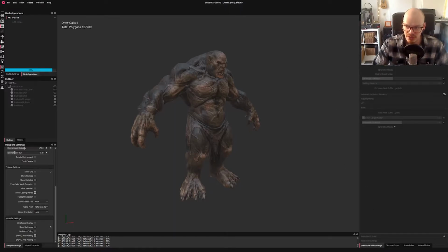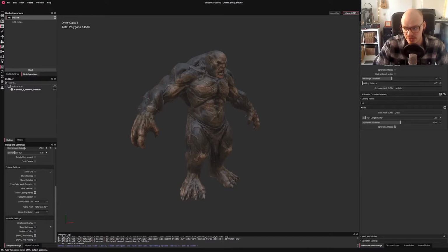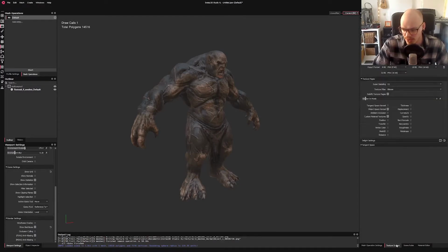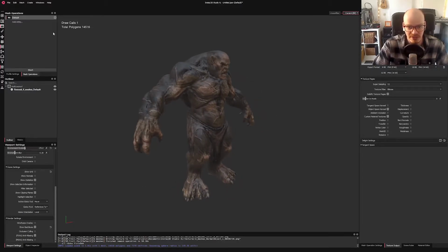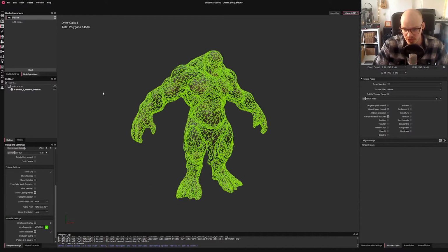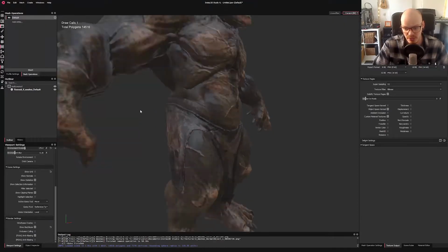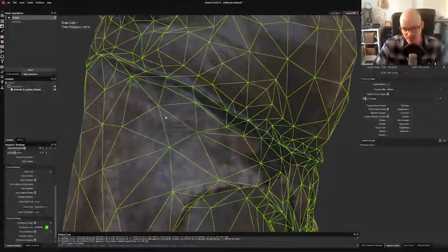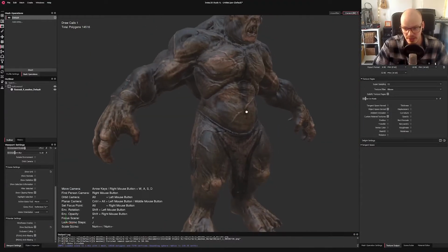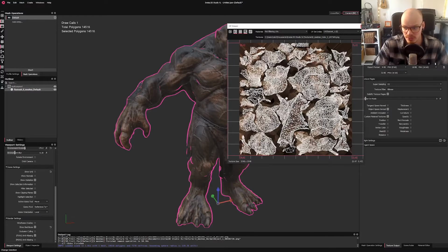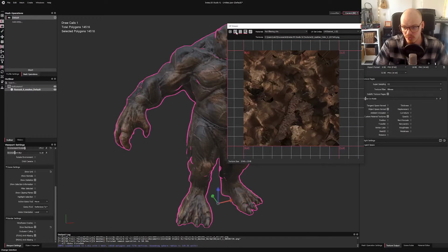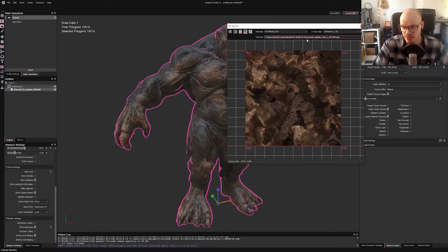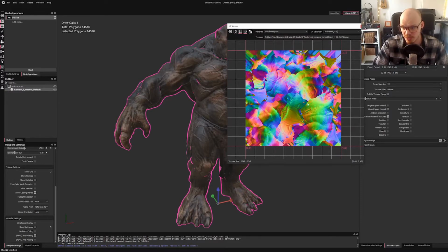So if you're interested in finding out more about InstaLOD's remesher, I do highly recommend checking out our knowledge base or YouTube channel, because today we're not going to look at these settings in too much detail. Here we've got the result of 14,000 polygons, so an almost 90% reduction down to just 10%. We've got a single watertight mesh here, modeled over these different parts, and in this case, one single UV layout with one single color texture, 2K, and a normal map. There we go.